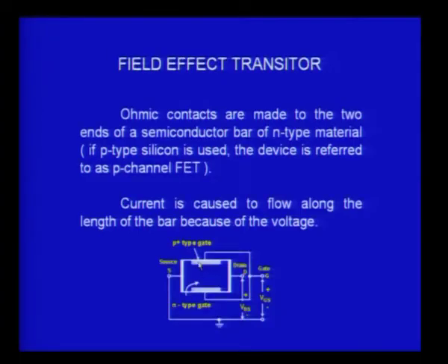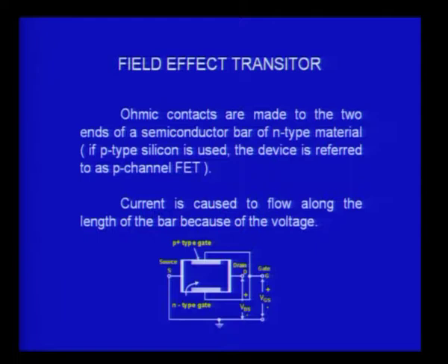The difference between this and the UJT is that in the UJT, the P type region is a very small region, almost near the middle of the N channel, whereas in this case it will be reasonably over a region, and more importantly this P type will be all through like a belt around the silicon block that I consider. So you will have a P region all around, and that provides the gate region. That is what is shown in this picture.